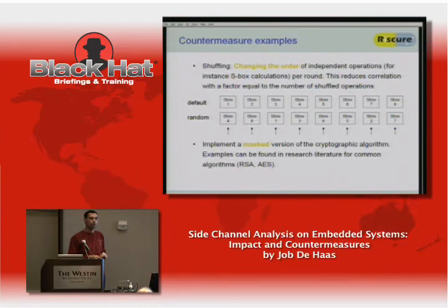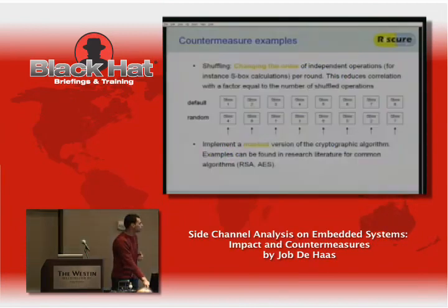Even masked implementations can be broken using side channel. Only the level of expertise and the advancedness of it goes up quite significantly. What you'll see is also that everyone is stacking all these countermeasures. So no one is doing only one thing and depending on it. It's very much a thing of combining a lot of these things. We have seen things like introducing full false cryptos in between the real crypto, just to confuse an attacker and make the correlation attack much more difficult.